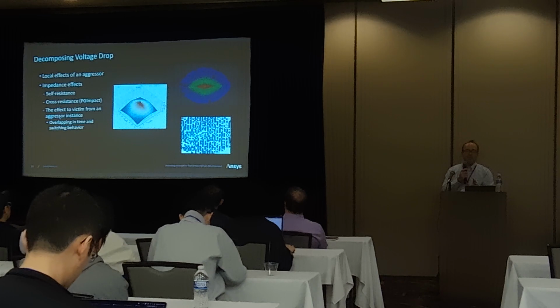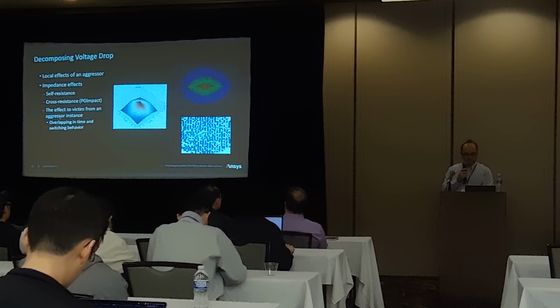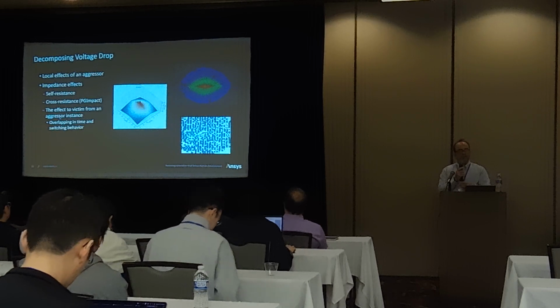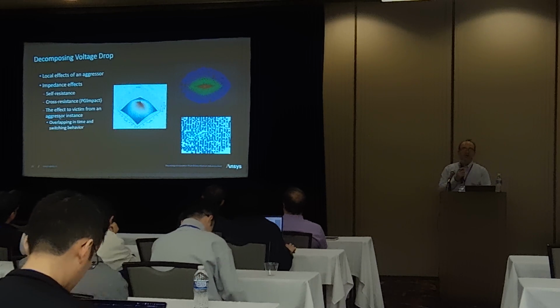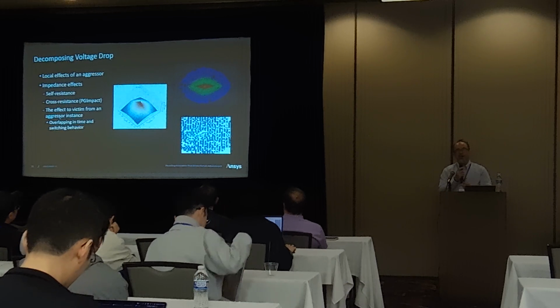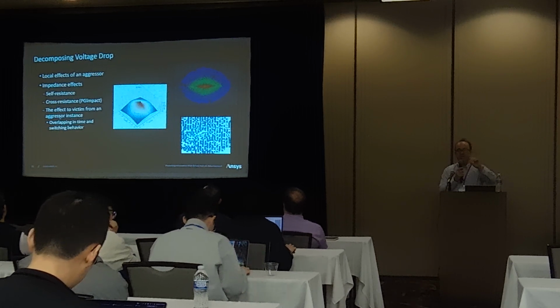But it shows you can create analytics if you have the resistances, then you can export them, or you can understand and create voltage impacts off of them by using simple electrical modeling of IR. And you need to think about whether they are going to be switching in time together, whether they are going to be switching in logic behavior. Maybe things are going to be switching in the opposite direction, or a one-hot condition, or not. So there's going to be a lot of possibilities, but at least we could isolate this to a gate behavior so that we can scalably understand a lot of things.